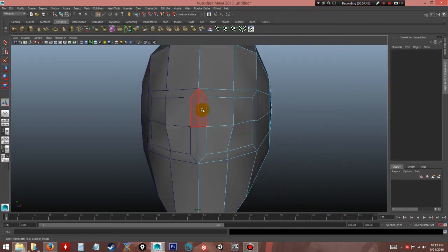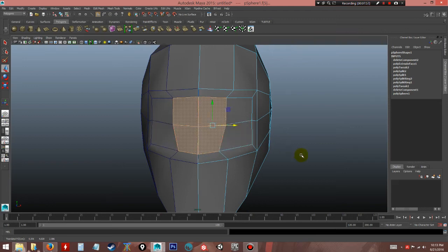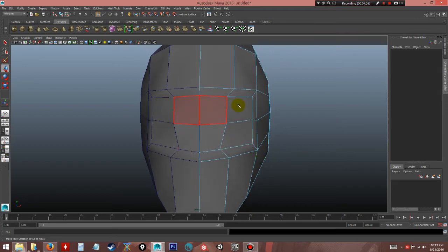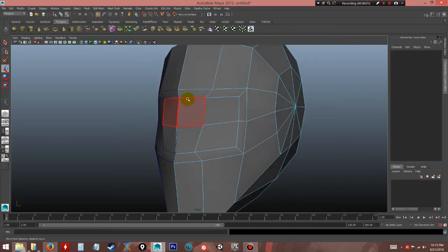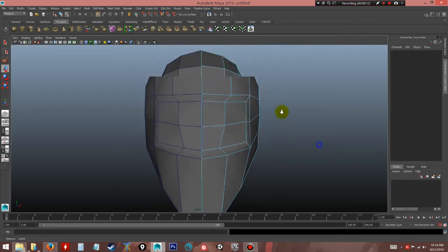The thing is, I want to delete these faces at the center because I want this to merge together. Right, so I will be pulling this, go to move, and I will close the gap. As you can see, now it looks like one whole visor together with a frame that is connecting with each other from left to right, instead of having individual framing.